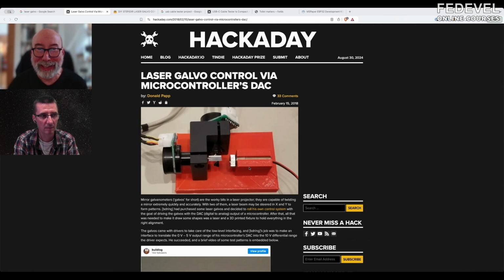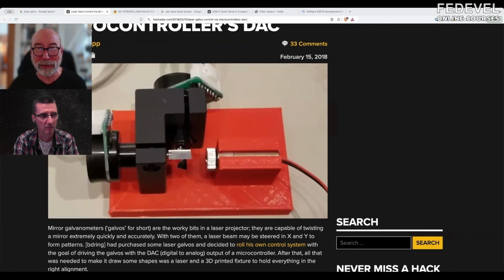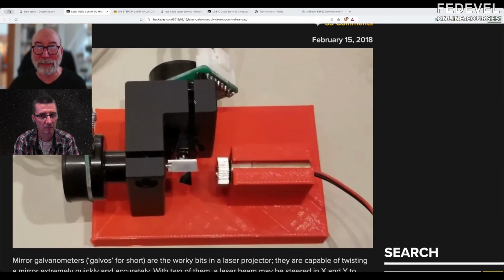They're really cool. One of the difficult things is actually driving these galvos. So you get these driver boards that can drive these at really high speed. And there's all sorts of potentiometers for tuning the parameters and overshoot and undershoot and dampening to get the fastest speed you can without getting really wiggly lines. So it's quite a challenging project. You can get really expensive versions of these laser galvos. They go up to thousands of pounds for really high-end ones.